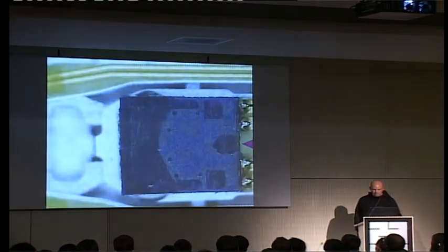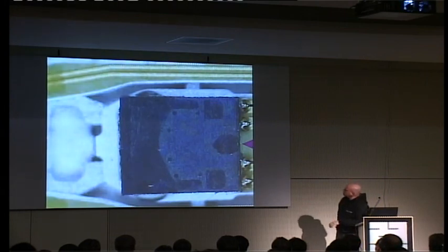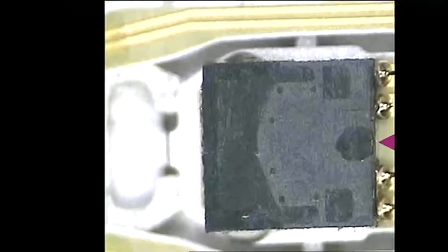Now we start to look a bit at how the heads look. Here we have a read-write head of a hard drive, a damaged one. I think you can see it there. It's pretty dirty. And this little triangle on the right side tells you where the actual sensor is. We are looking from the flat side, the side that actually flies over the surface, at a slider. And this black thing that you can see with your bare eyes is not the head, actually, it's a slider. And the head is on the front side of it, rotated by 90 degrees. That's where the leads come in.